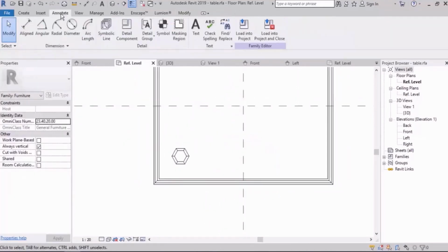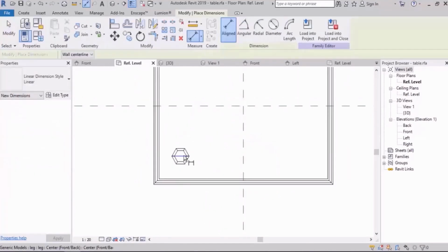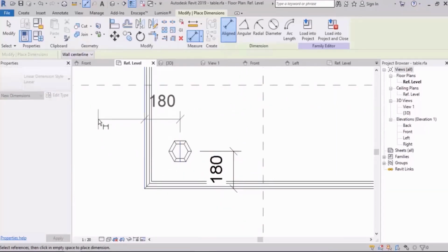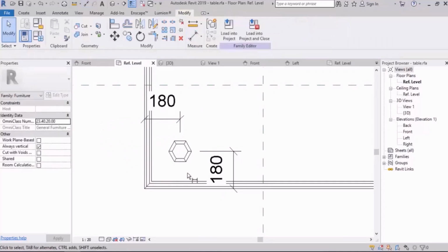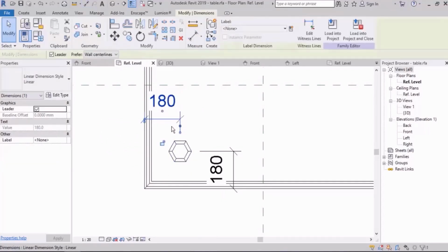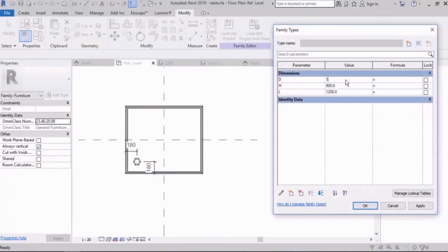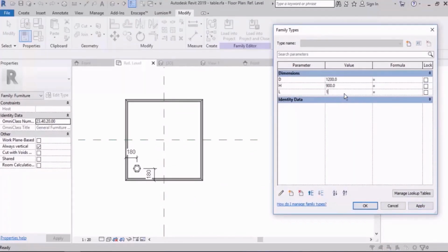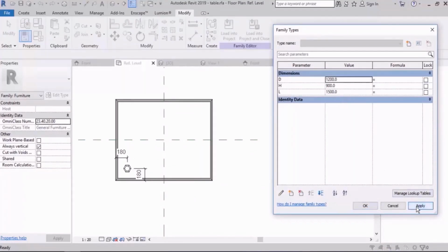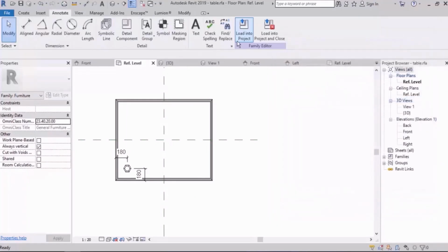Well, now, what's the benefit? What's the advantage? It's that you can make this parametric in this zone. And if you want, you can also draw a reference plane. I'll lock these. Now check this out. Very simple, really, very, very simple. Very professional. Now, just like I said, it is called nested family. Let me write it down for you.